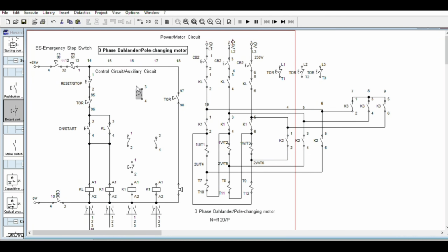Let's say for example in a turning machine, there is an option there for automatic and semi-automatic transition. You will use the manual lever switch for low speed and high speed. We need interlock here and we need the normally closed push button. This is double interlock always. One of this contactor will interlock this one.